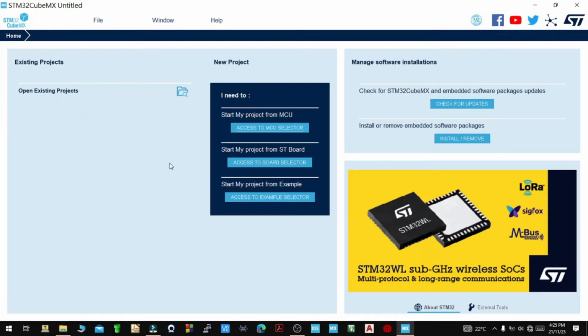So we are used to connecting TX to RX and RX to TX. So in this case, the producers have inverted their naming. That means you have got to connect the TX to TX and the RX to RX pin.